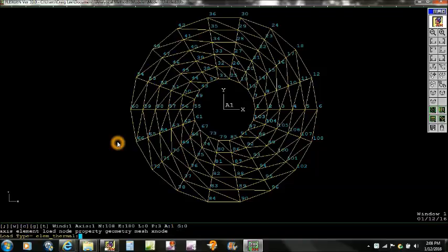Now I'm going to insert a load, and we're going to put it over here on node 6. That'll be the cylinder touching the wall here. And that's going to be an element thermal load. The temperature of that is going to be just a fixed temperature of 100 degrees C, and it'll be on node 6.